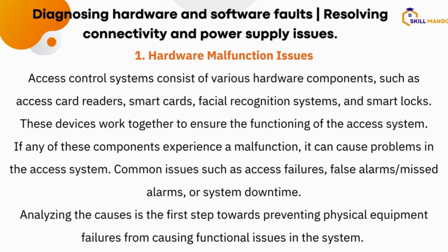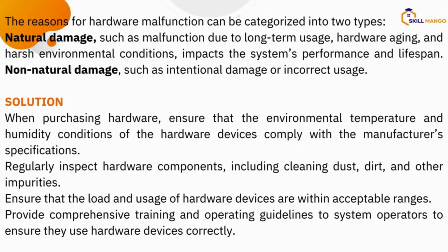Ensure you have the right power supply. If, for instance, the total requirement is about 12 volts, 2 amps, you can do 12 volts, 4 amps, so you can have failures and redundancy. So you won't overpower your power supply, for it not to fail or start giving you problems. All right. So you have to read up on the write-up to understand the theory better.